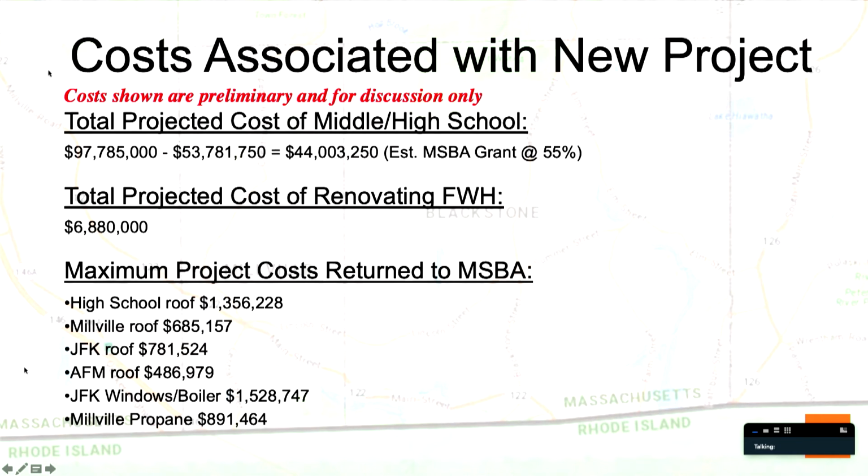Yes, sir. I just saw number 430 a square foot, but before that, we were looking at like 6 and change. How did we get back to 400? 400, mostly interior reno. So the 600 number was just pure exterior site? No, that's everything. It's building and site, a new building, or building and reno. The Hartnett, if you follow through the logic on that page, it's interior on the lower level of this building, not rearranging interior walls, but cutting the slab and getting toilets in those rooms and connecting out to the sanitary sewer. So it's almost all interior work, what we would consider about mid-range renovation.